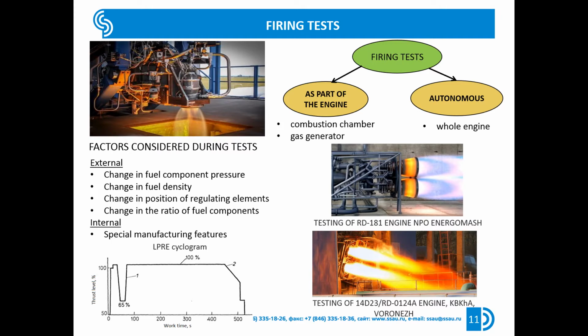Only this type of test can give maximum information on the performance of the LPRE and its actual characteristics. During these tests, each unit works under real conditions, similar to operating conditions, and the mutual influence of the units on each other is automatically taken into account. When performing fire tests, start-up and shut-down cycles are selected. The actual characteristics of the LPRE and their stability during the specified life cycle are determined, and the LPRE's reliability and performance during operation in the propulsion system are assessed.